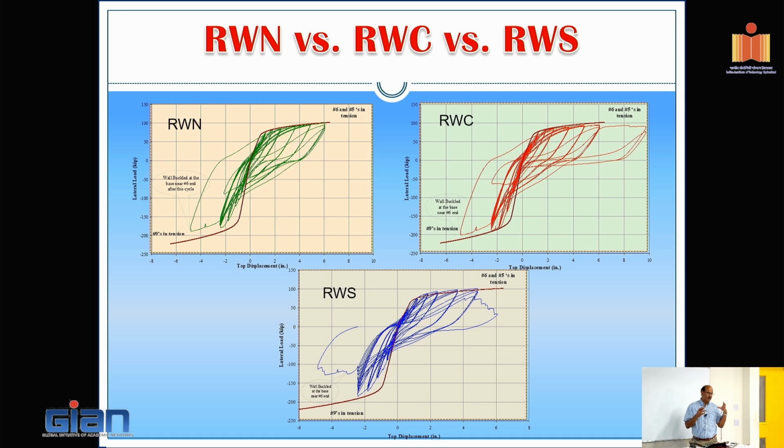The reason it gets fatter is that your strain concentration exercises more plastic action, which doesn't mean it's a good thing. It's not a bad thing, but you can potentially prematurely fail the rebar. People misinterpret when they say higher strength, fatter loop is a good thing. But the premature failure can be a bad thing if you don't pay attention to that.